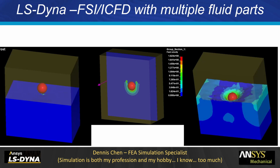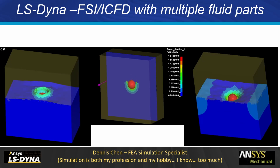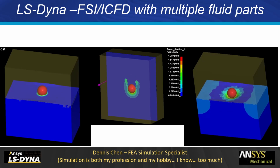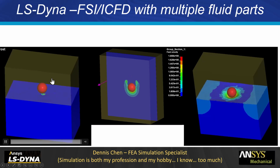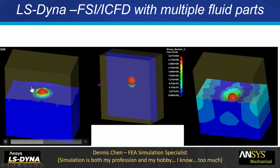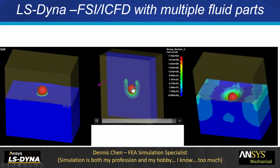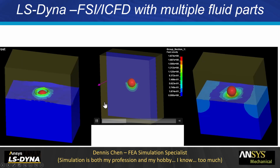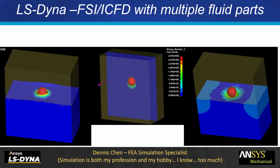All right. Today let's look at doing CFD and FSI analysis in LS-Dyna for a multi-phase flow problem, where you basically have more than one fluid material. A typical example is, say, dropping a steel ball into water, or in this case, something much more viscous, and then I can look at the flow pressure. I can also couple very easily to the structural solver for LS-Dyna.